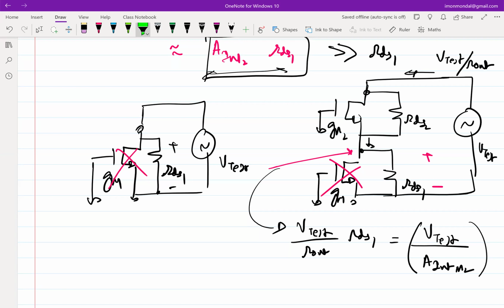Okay, so let me answer that question. Her question is, why am I directing the low voltage swing to high output impedance? That relationship is not true all the time. What I'm trying to do is figure out how much incremental current is appearing. In the circuit on the left, I'm doing an apples to apples comparison, in the sense that in both cases I will look at M1 and see what current is flowing through M1.